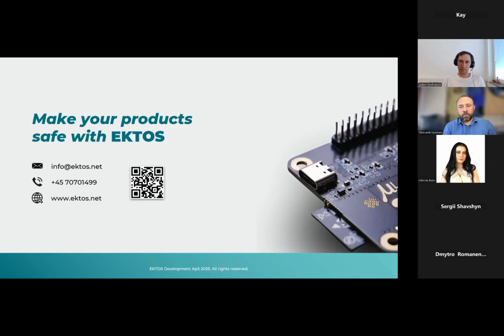Another way would be to do it all over again, not necessarily developing everything from scratch, but at least we need to start generating all the process artifacts. We need to start doing the architectural design. We need to calculate all the required diagnostic coverage, generate FMEA and stuff like that. And only then can we start applying this already existing product to be compliant with newly introduced safety requirements. So these are the two ways to go, basically.